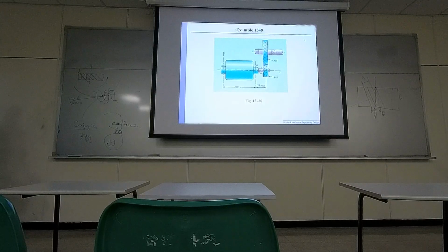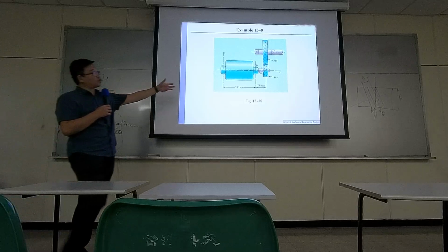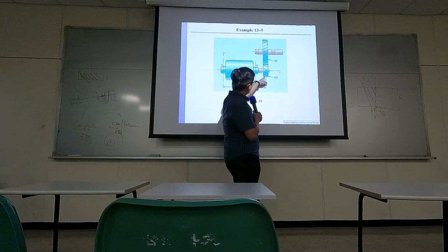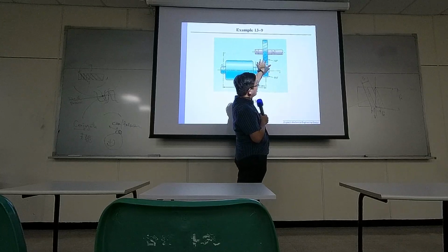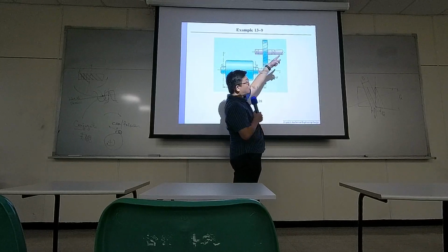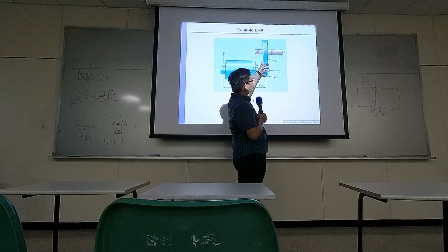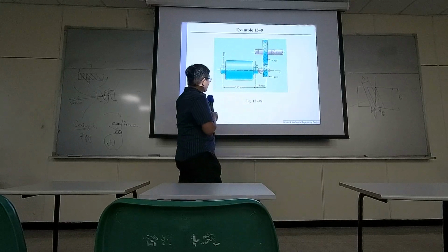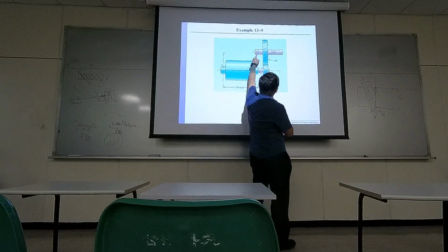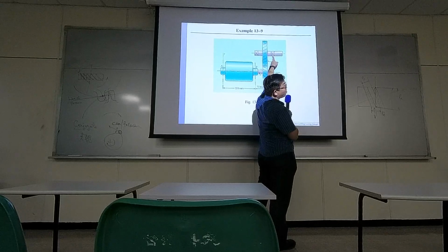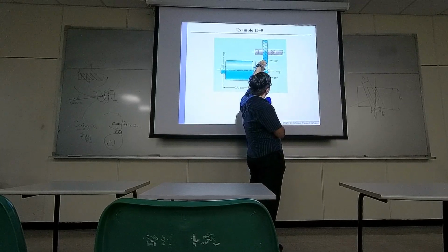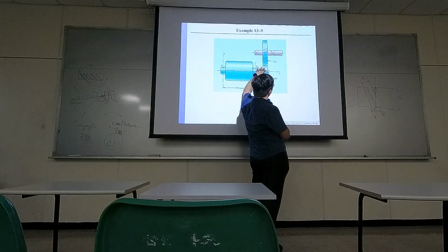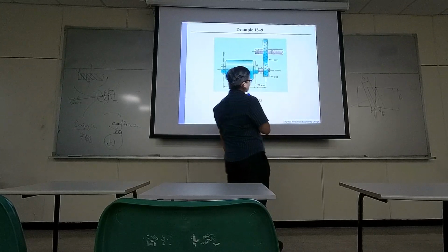So this is the exact example that I mentioned. We have a motor that is driving a pinion, and this pinion is driving a gear, and there's a shaft on the gear. This problem may be asking, what would be the reaction forces for the bearing? Then you need to figure out how much force is being applied between the pinion and the gear.